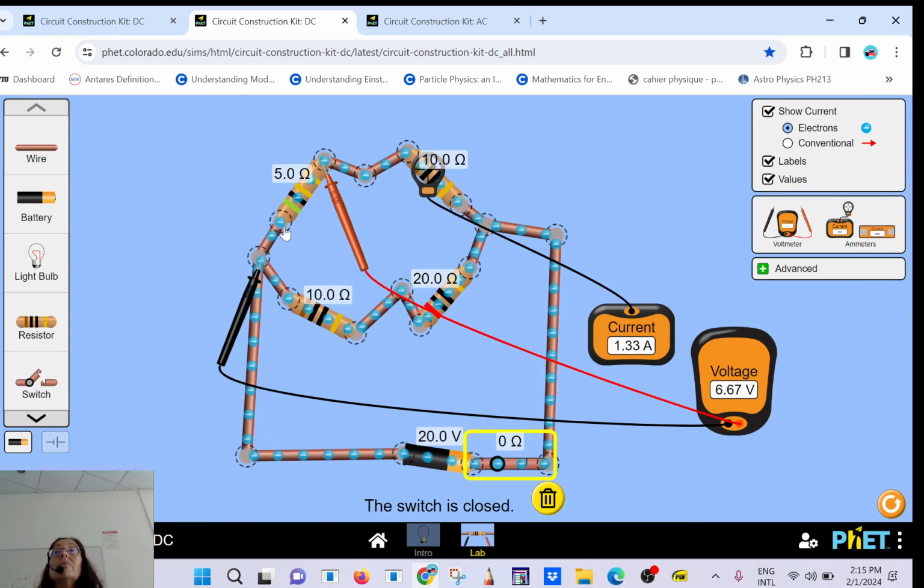Why did you put the V RMS equal to 0.7? Because that's the definition of the RMS current. But here you didn't use it, because you used Ohm's law. However, if I want to find the peak current, how can I find it? It's 3 divided by 0.7. So what do you get? 4.8.